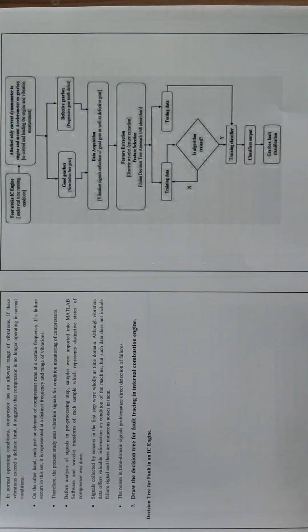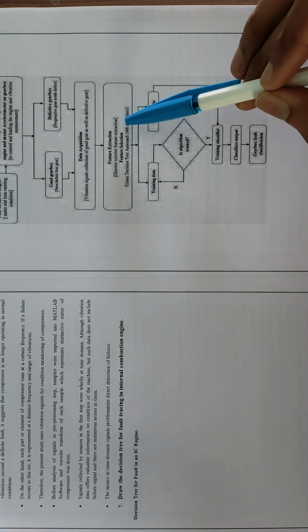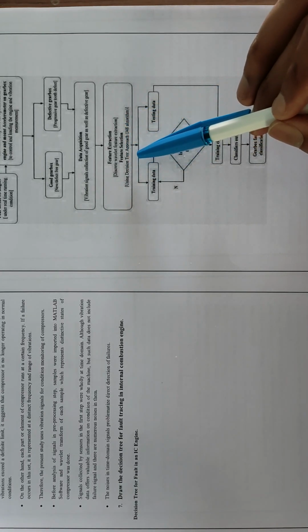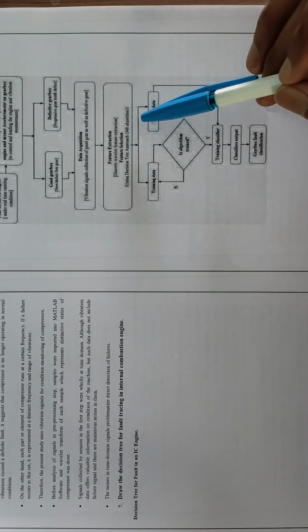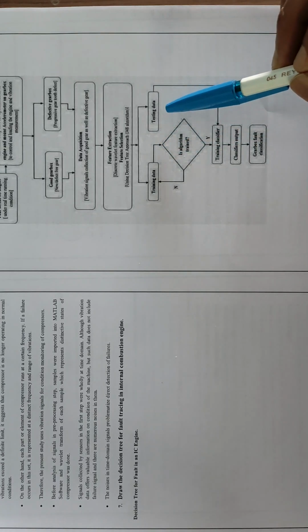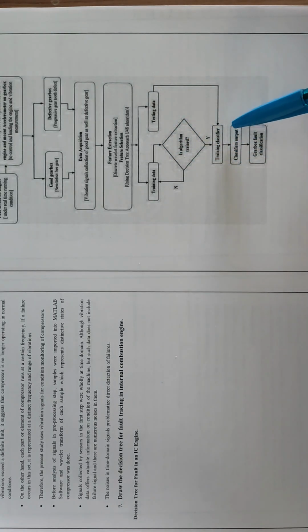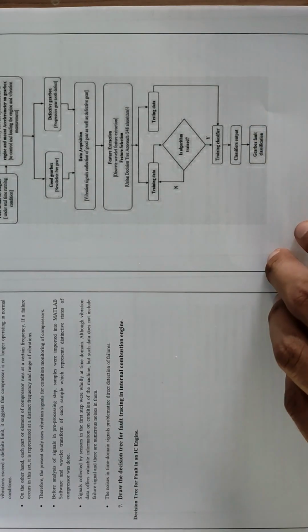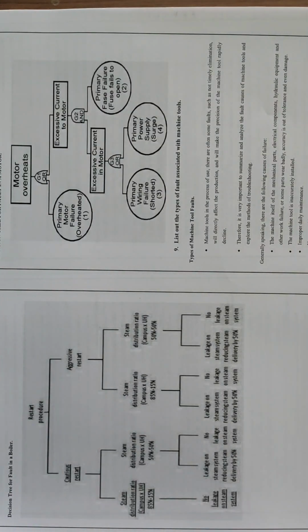Good gearbox, new defect-free gear, defective gearbox, progressive gear defect, data acquisition, vibration signals, collection of good gear as well as defective gear, feature extraction, discrete wavelet feature extraction, feature selection using decision tree approach, J48 algorithm, training data, testing data, and the algorithm trained by training data. Classifier's output: gearbox fault classification.